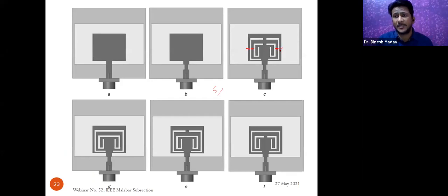It has not been shown in this diagram because for the sinusoidal or time-varying current that is coming, it is shorted. There is no open circuit for that, because we are talking about the antenna. The antenna behaves such that, because the capacitor is here, it allows the surface current to flow here also and here also. But the switches would be biased through the inductor. An inductor allows DC to pass and blocks AC, so the AC does not come out of the structure. That means you can save the efficiency of the antenna.